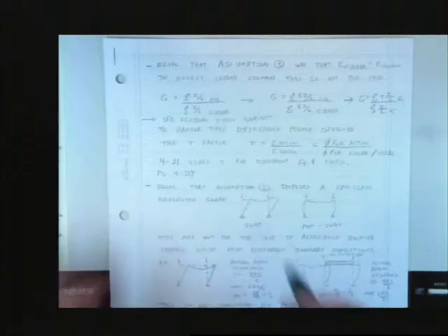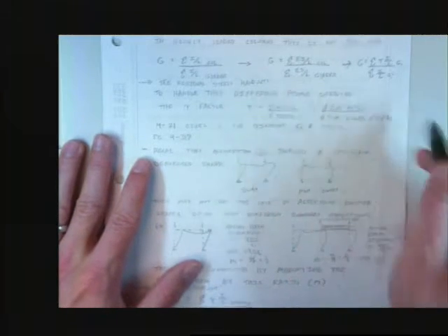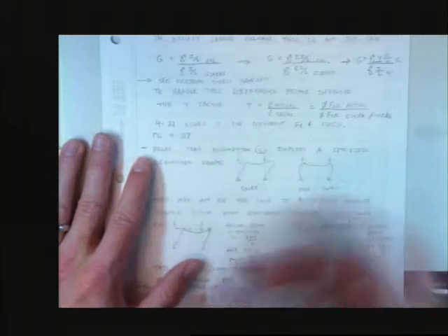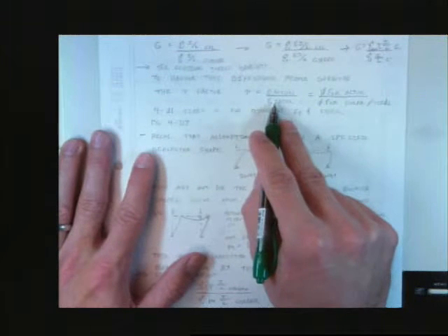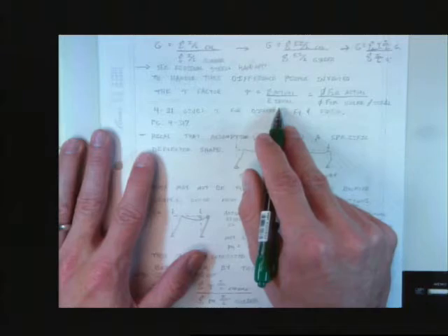But recall that assumption 1, the one we were just talking about, was that E girder is equal to E column. For low-loaded columns, that's a great assumption. But for high-loaded columns, as I just showed on the previous page, it's a bad assumption. So if we bring this E back, E on the top and E on the bottom, we're going to use something called the tau factor. What the tau factor does is it's really the ratio of the actual E over the ideal E.